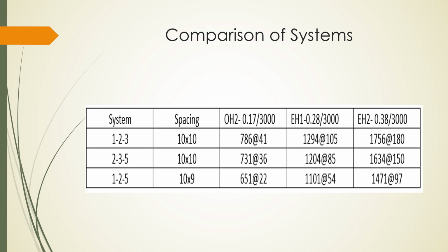And even the 1471 at 97, that's doable. That's a pretty beefy sprinkler system. And again, that doesn't include friction losses back to the base of the riser or elevation losses as well. So we can make some judgment about these systems now that we've had a chance to come up with some rough numbers as to what the system will require for adequacy.